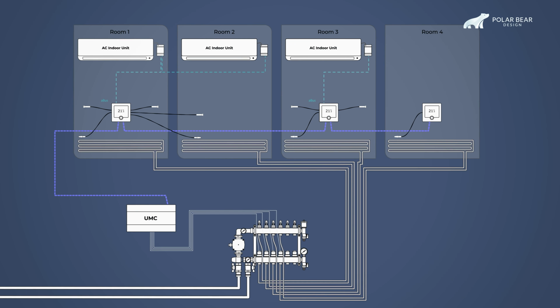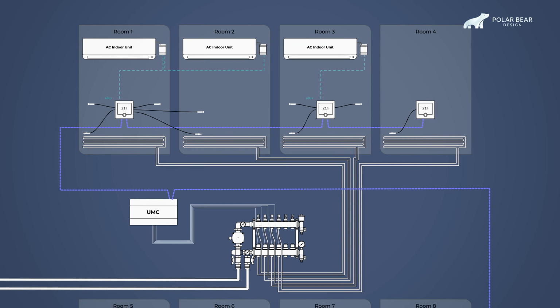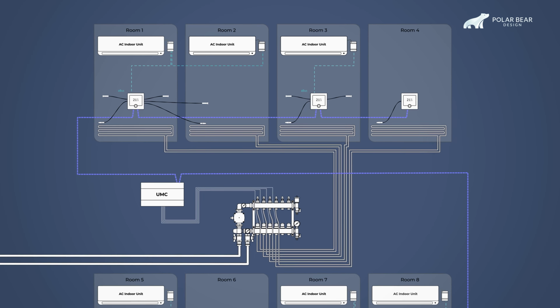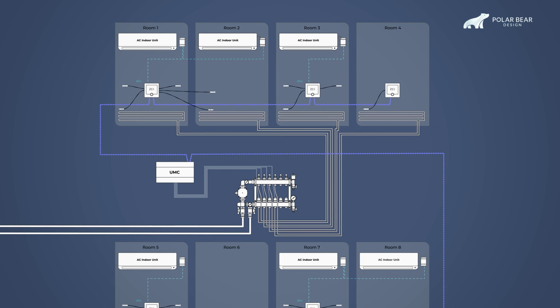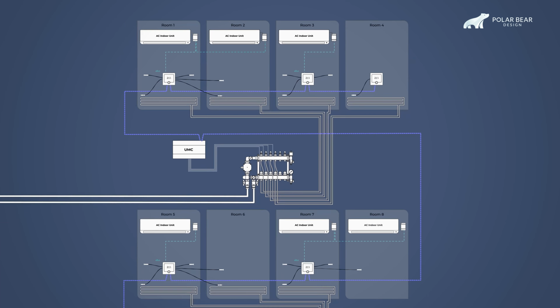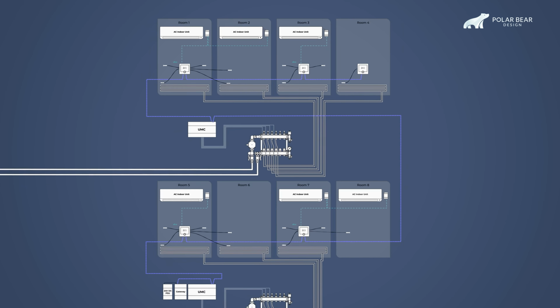So, our thermostats have a rich feature set that can simplify complex heating and cooling and distill the control down to one super intuitive dial. They can be used in isolation or linked together. So just how big can a system get? Well, we can host up to 32 devices. That's any combination of thermostats and UMCs per bus. That's potentially up to 64 zones of climate control.